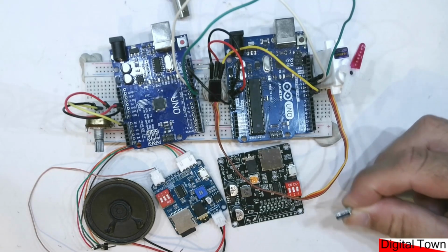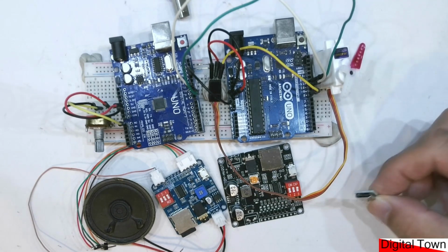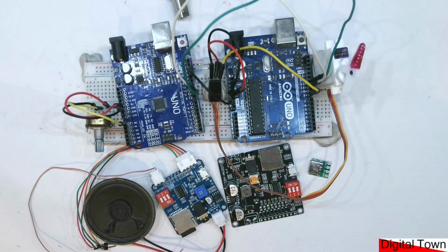This is a USB-C connector. Now, this one, although USB-C has lots of other little things that it can do, at its absolute basics, you can see that this connector has got a ground, a VCC, and 2 digital connections, which are actually for the signal. So we can send serial communication over USB. In fact, that's its name, Universal Serial Bus.